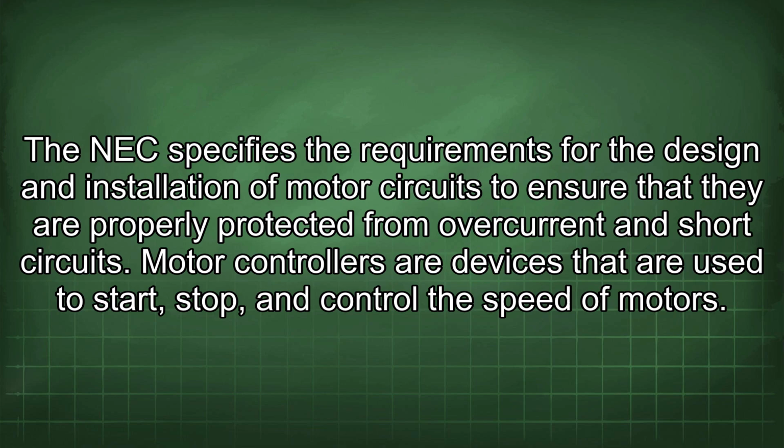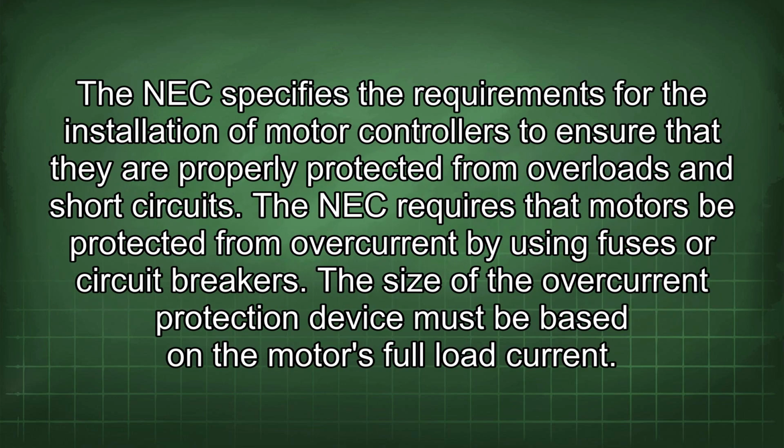Motor controllers are devices that are used to start, stop, and control the speed of motors. The NEC specifies the requirements for the installation of motor controllers to ensure that they are properly protected from overloads and short circuits. The NEC requires that motors be protected from overcurrent by using fuses or circuit breakers.